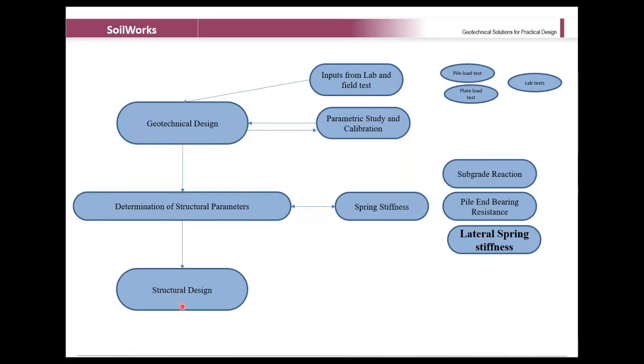For the structural engineer, it is his job to perform the analysis to find the forces in your foundation, followed by design of your foundation. In between, we have one particular thing, that is determination of structural parameters. Basically, the structural engineer designs the foundations, like calculating the rebars and everything. In order to calculate the rebar, we need to provide certain stiffness for your springs, which act like the soil in the structural software. So in order to determine your structural parameters, we need to have a spring stiffness.